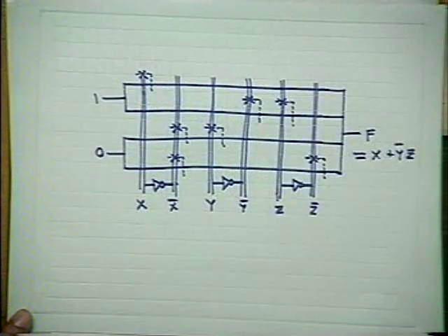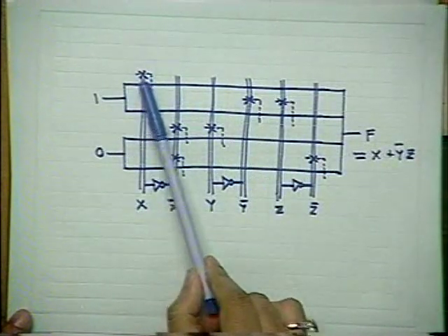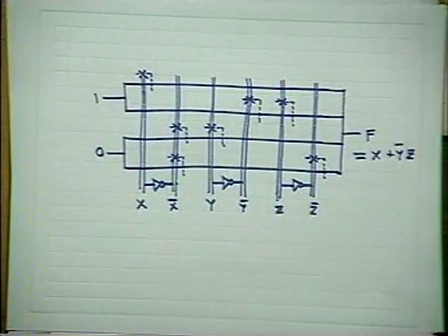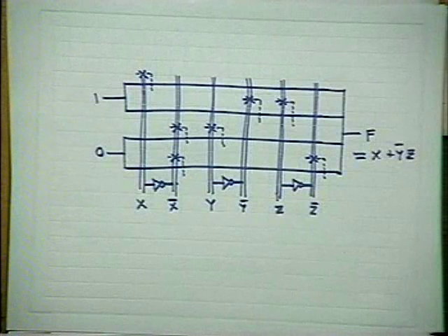Another thing is normally done. At each intersection, below this, there is a transistor. When I actually develop the chip, I will just arrange a matrix of MOSFETs. These MOSFETs will all be located below, but they are not connected. Only those which are useful, you connect them. That means you have to have personalization only at which level? Metal, via hole etching and poly level, because you have to etch at certain locations.